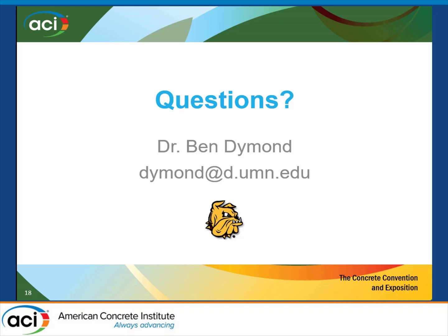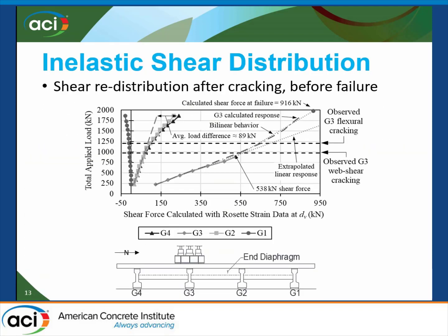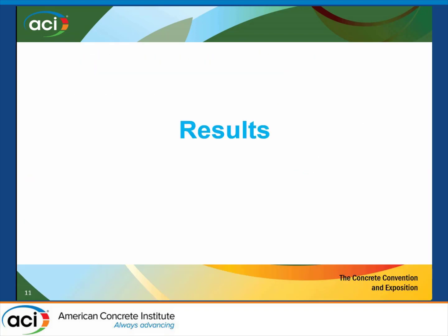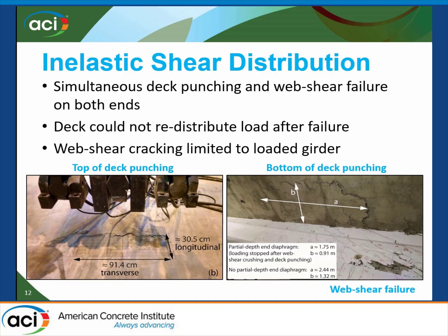The loading that you placed over top of the girder, you had 3 actuators. Were they lined up on the center line of the girder, or was there a diagram here? Well, just go back one slide. Oh, the applied load, right there. It looks like they were applied on either side of it, and so you have stiffness of the loading frame itself. Did that influence the punching shear? Did the loading rig actually flex and cause the punching shear?